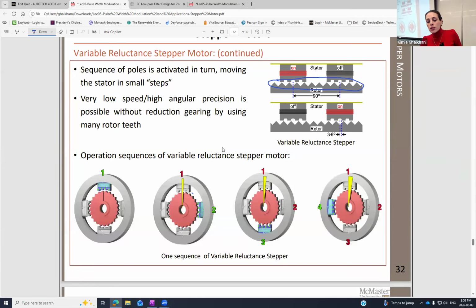If this is maximized, the same teeth in here are maximized in here. If the teeth are in variable positions relative to the poles, they are going to generate variable reluctance. Therefore, the principle of variable reluctance, as I said, is dependent on the position of these teeth toward the pole.